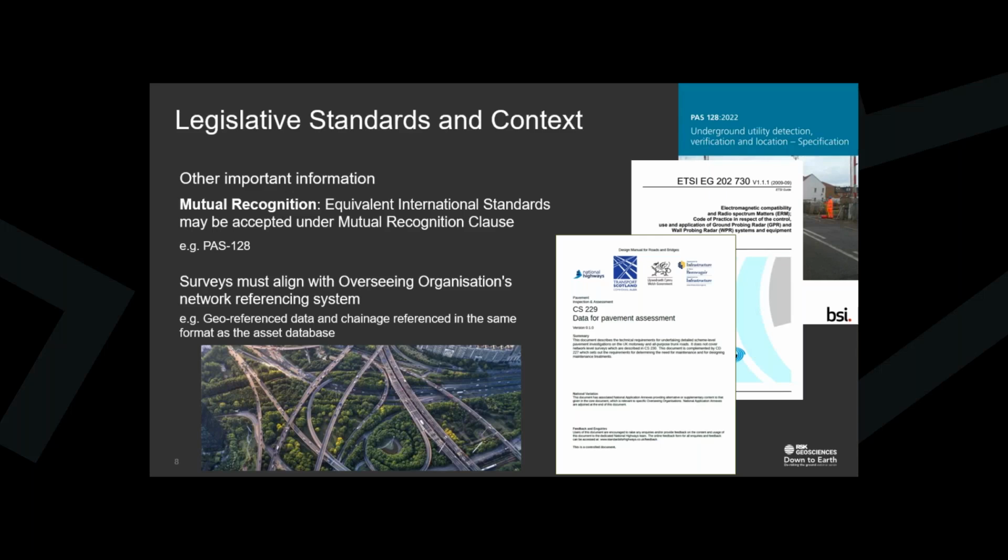European standards, there is the ETSI EG 202 730 to ensure the equipment is safe, interoperable and legally compliant. The ETSI standard sets out approved frequency ranges and power limits for the equipment. It sets out operational safety to prevent interference with other systems, and it also outlines best practice for survey methodology and data handling within Europe.